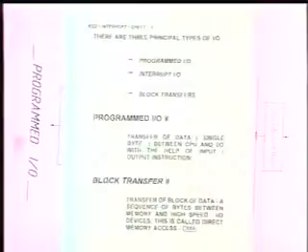Now, the first statement I made is that normally the peripherals are slower than the CPU. So in this case, one has to go for programmed I/O. There is another case of transfer where you want to transfer a block of data, which is a sequence of bytes, between the memory and a high-speed device.